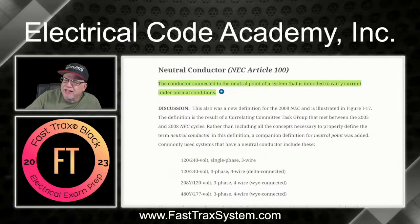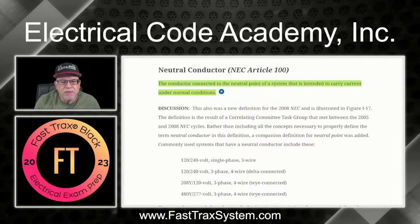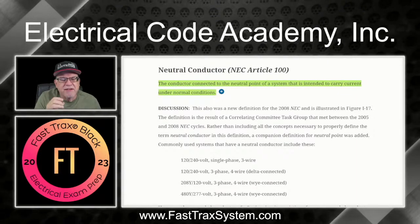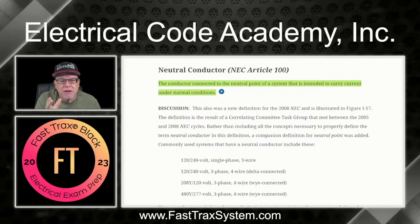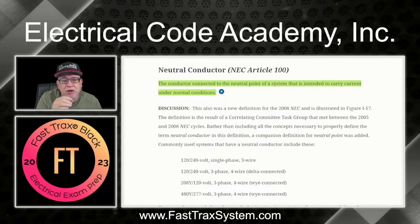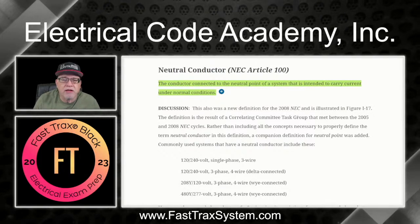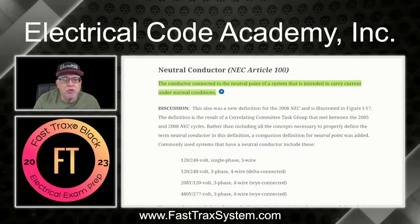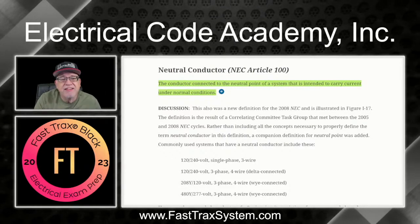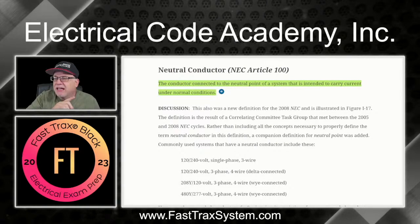Rather than go through all of the explanation of a neutral conductor, we need to show on the system, whether it's a Y transformer or delta transformer, or a delta that creates a zigzag secondary system, what connection creates a neutral. And then it's important to make sure people are aware of what does not create a neutral. Even though a conductor is connected to earth, based on where it's connected on the transformer, it doesn't necessarily make it a neutral, but it is still a grounded conductor because it's intentionally grounded to the earth through the system. So all those things are important.